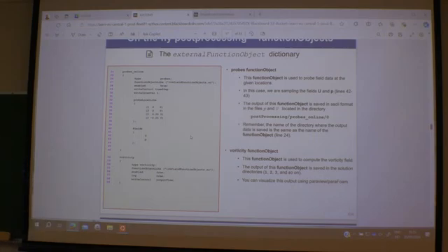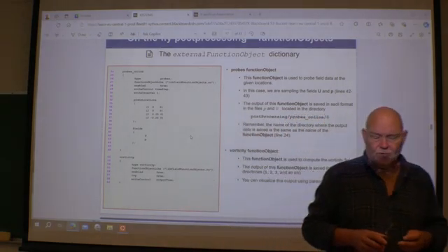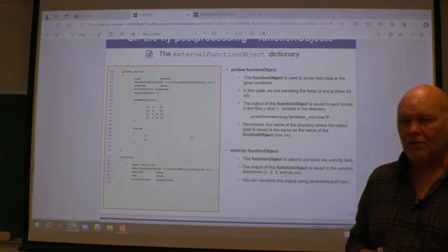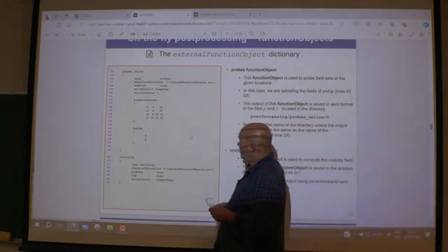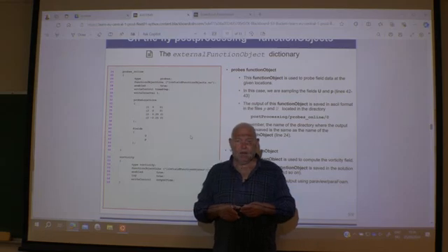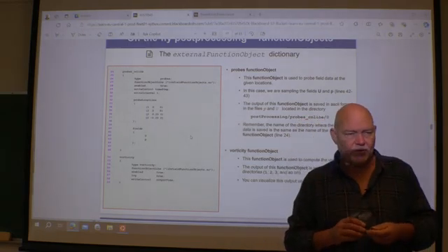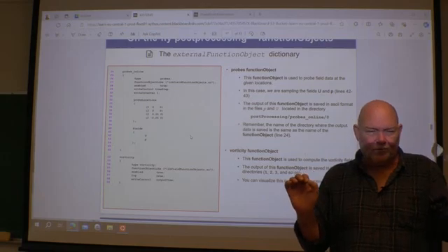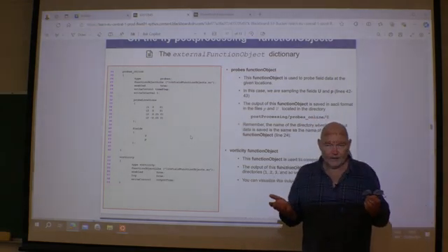And then we have something nice here. We have something probing. This can be very, very useful. Say you want to do a grid convergence index check for your mesh, and then you can here specify locations for what to print out. And I mean, typically when you do a grid convergence index, you have to find good monitors, find good locations that sort of cover the physics inside your problem.